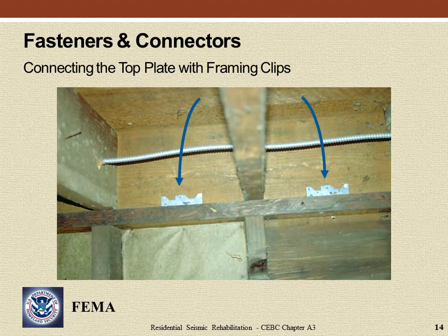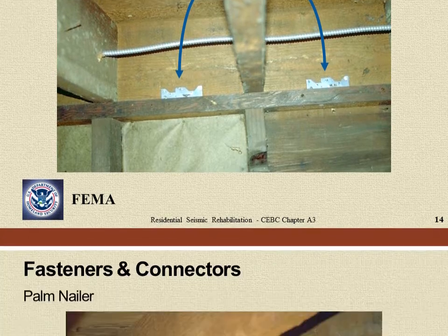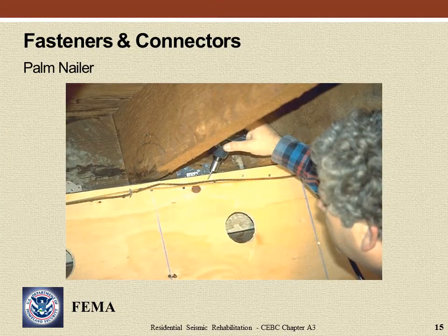This photo shows framing clips connecting floor framing to cripple wall top plates. In locations with limited access, use of a palm nailer is helpful for installing required connectors.